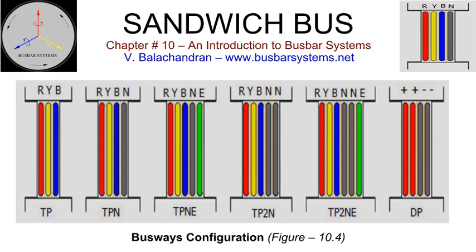In the majority of cases, an earth bus runs outside, clamped to the enclosure. In some cases, the specification calls for protective earth to run inside the enclosure. Often, the cross-section of the protective earth is the same as that of the phase conductor. Depending upon the design, this can be made thinner to meet the specification requirement.